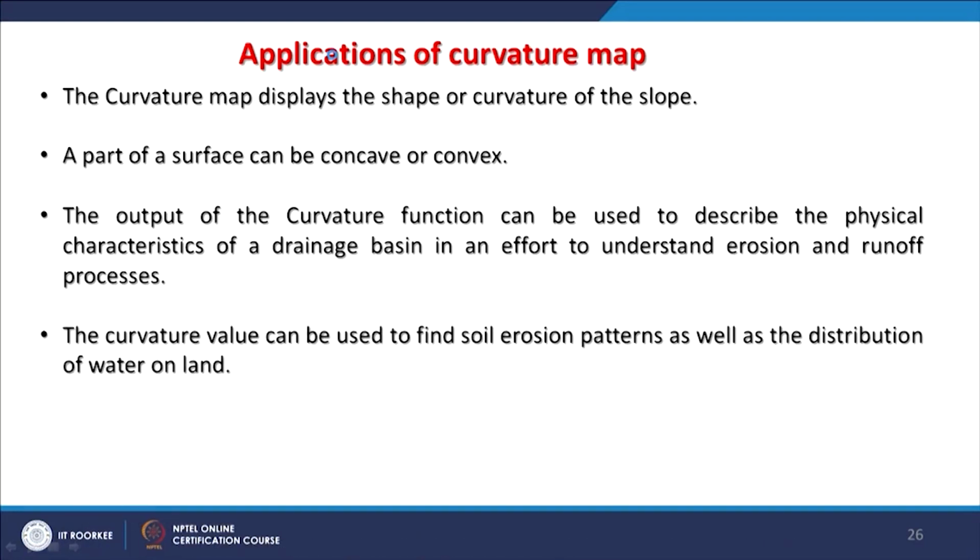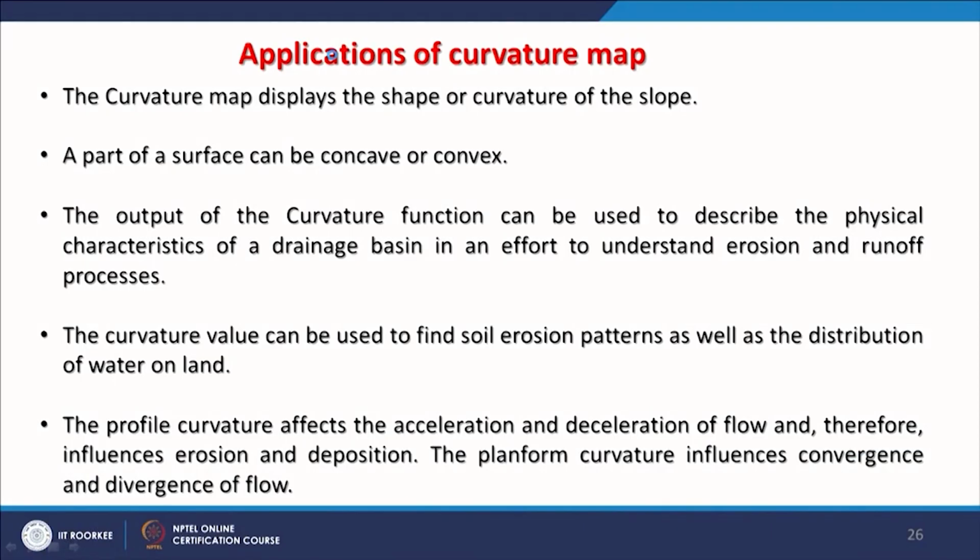And these curvature values can be used to find soil erosion patterns as well as distribution of water on land, or even in landslide studies. Profile curvature affects the acceleration and deceleration of flow, mainly water flow, and therefore influences erosion and deposition. Plan form curvature influences convergence and divergence of flows.